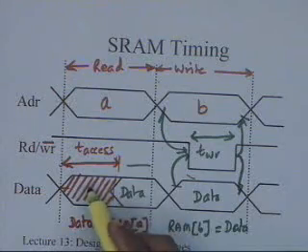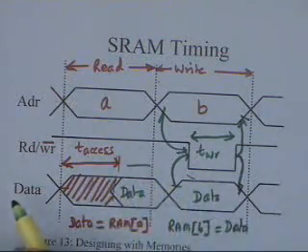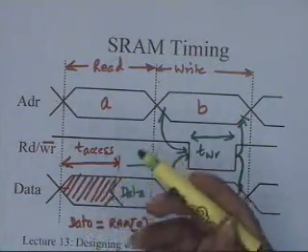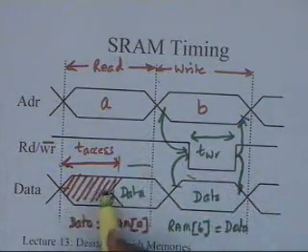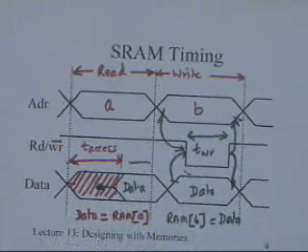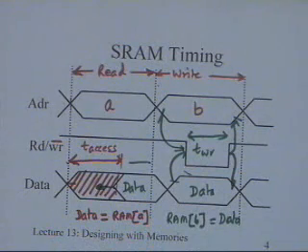For some locations, and also it depends upon what was the previous location, how the chip select, how is the decoding being done and so on, this could come earlier than that. But this T access ensures that after T access the data corresponds to the location that you are trying to read. That is the important time. So does that answer that question?